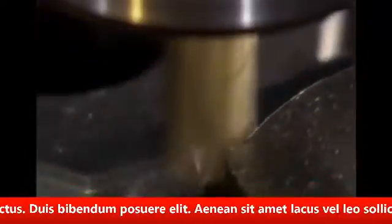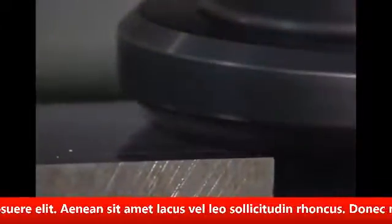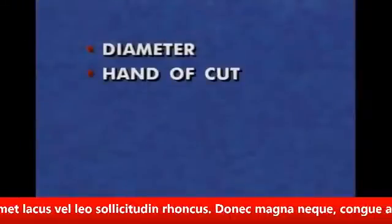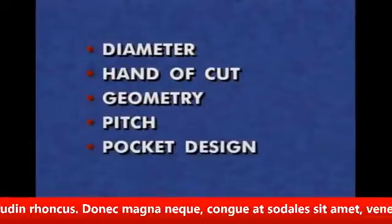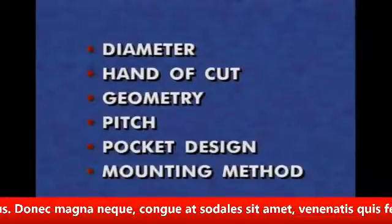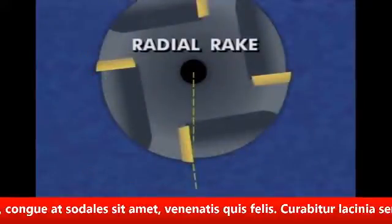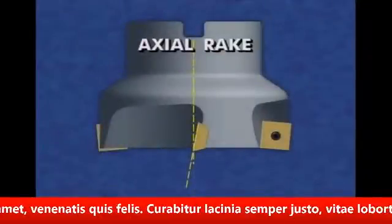Multi-point tools rotate to cut. Face milling cutters are a type of multi-point tool. Face milling cutters vary in diameter, hand of cut, geometry, pitch, insert pocket design, and mounting method. The two rake angles determined by face milling cutter bodies are the radial rake and the axial rake.